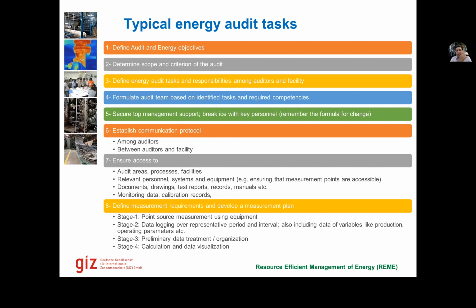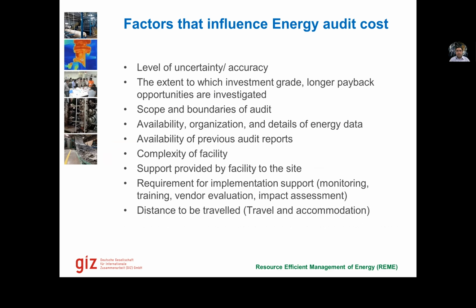Stage 2 could be a data logging. So rather than inserting the probe once and only measuring the point source emissions, we could install a data logger there, which could take profile of 2, 3, 4 days, and for the same time we could have the production data as well, and then we could make energy performance indicators. Stage 3 would be then to organize this data, analyze the data, identifying the areas of improvement, and then doing the calculations and data visualizations in stage 4.